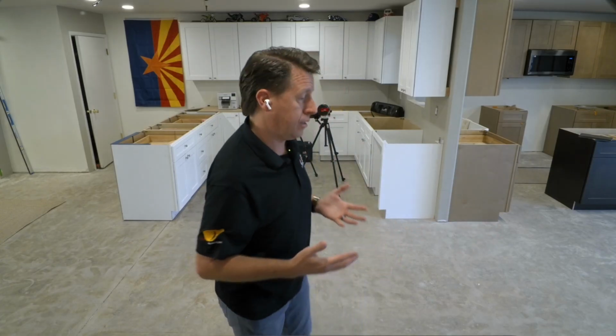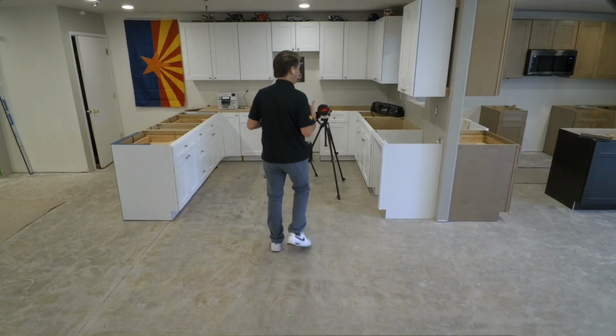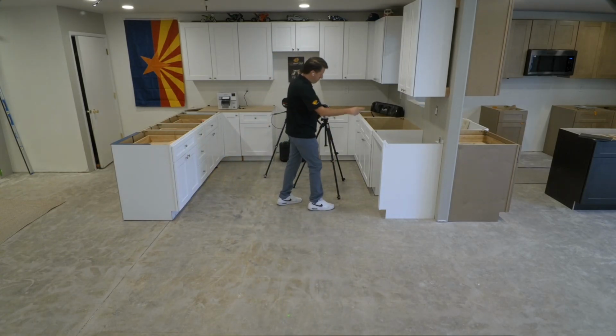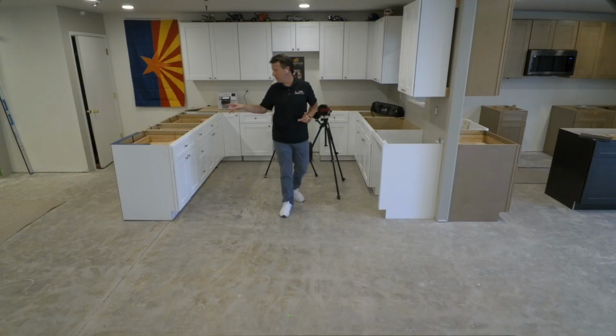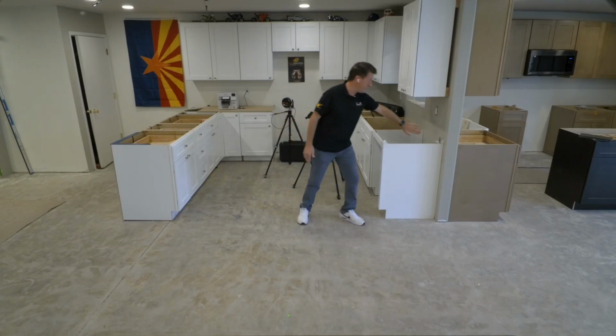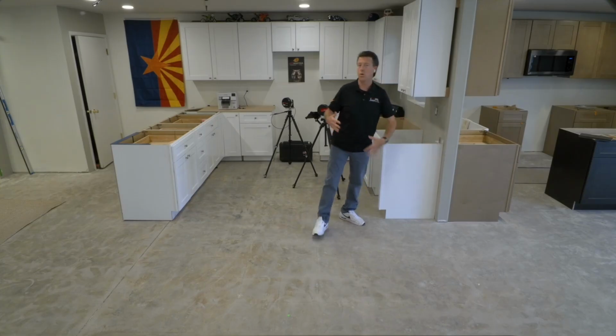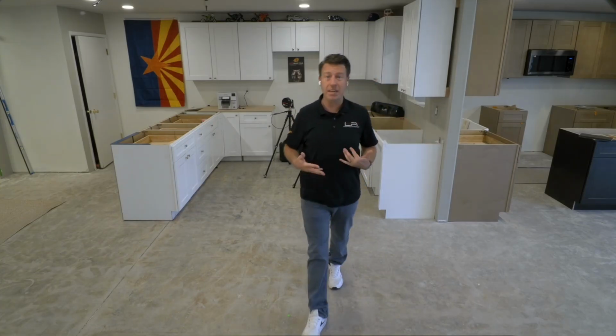It eliminates someone else later in the process needing to make some assumption. I like to finish that drawing if I'm templating, and scan around the room to see if there's any little detail I maybe forgot. Do I need a return for that finished edge to die correctly around this wall? Does the sink fit in the cabinet? Those kinds of things.